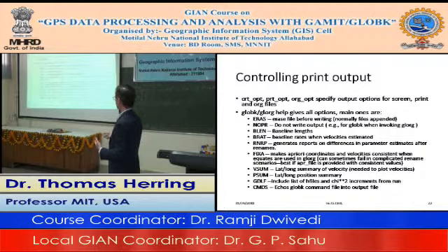And again, we recommend that if you equate parameters in glog, that the a priori coordinates be consistent between those two. VSUM outputs a lat long summary of velocities, and you need that if you're going to go on to plot velocities with things like shplotvel, for example. PSUM outputs a lat long summary of your position changes as well.